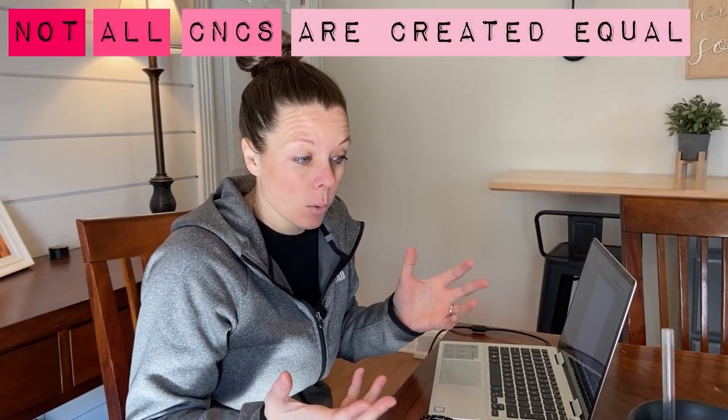And I will say, if you just look at the suggested speeds and feeds on the website, they are way more conservative because they're supposed to be safe for anyone running any type of CNC, and not all CNCs are created equal. But then if you download the tool database file from Bits and Bits, you're going to get the specific recommended speeds and feeds that can be handled by a Onefinity, which is typically seen as a machine that can push a little harder and run files a little faster. So that's a big bonus for buying from Bits and Bits.